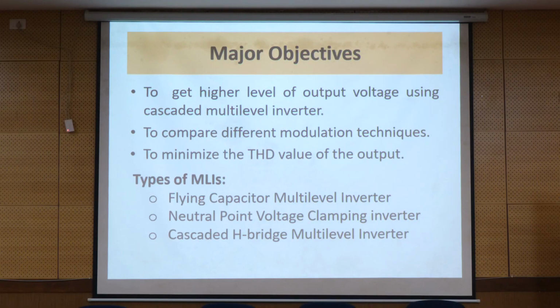No, that is the 3-level diode clamped multi-level inverter. That is the number of levels, and you will get 27 switching states, and 24 active states, and you have the small voltage, medium voltage, and large voltage vectors present.